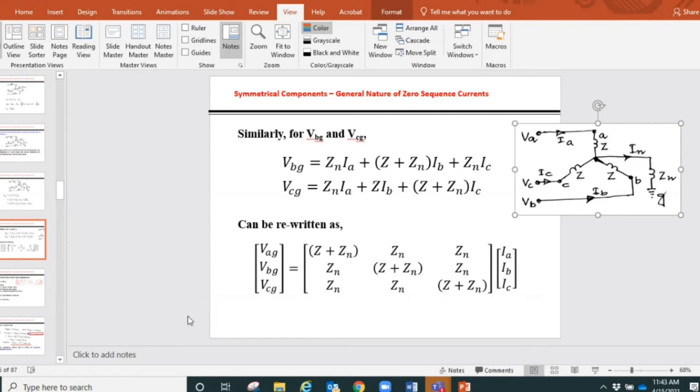And now that is what I was explaining, that impedance is not as straightforward as when we get sequence component voltages and currents. They are much more complicated. So what we see now looks like this matrix, where the voltages are here and the currents are here. So this is the V equals IZ equation, which is our normal equation. This is the impedance that will give us the positive, negative, and zero sequence impedances.